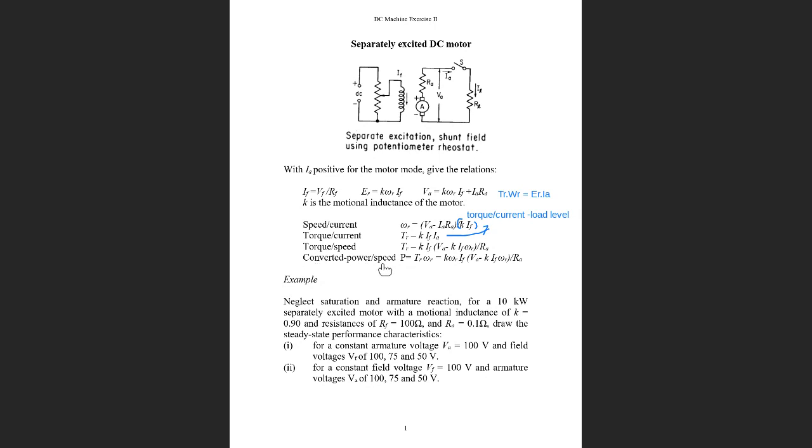And also there's the mechanical power, the product of the torque and the speed, in relation to the motor speed. So you look at the power. Generally, for a given applied voltage, when the speed is 0, the power will be 0.